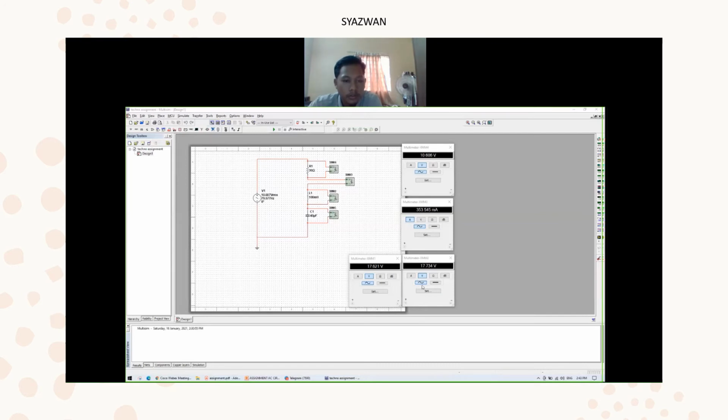Okay, today I would like to explain about simulation of series RLC circuit in resonance state. Firstly, we must draw a simple circuit of series RLC, in which the RLC components we must draw in one line. You can see here that we put the resistor 30 ohm, inductor 100 millihenry, capacitor 40 microfarad, and in the AC supply we put 10.607 VRMS